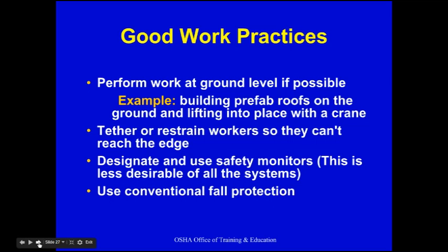Tether or restrain your workers so they can't reach the edge. That's with a full body harness. Use safety monitors. Again, this is the less desirable of the systems, but it's better than nothing. And whenever possible, use conventional fall protection means: guardrails, fall arrest systems, netting if necessary.